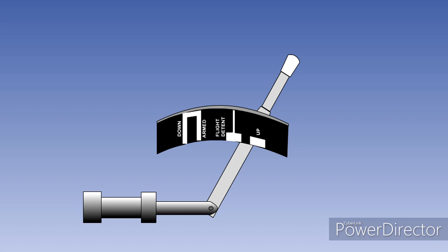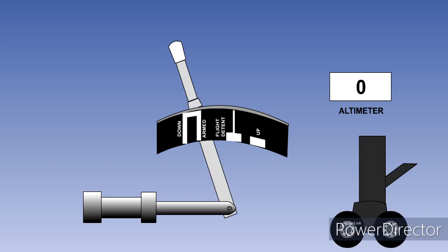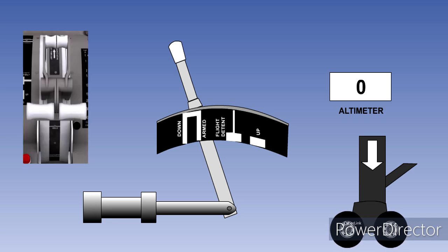Different aircraft types use various different parameters. They will usually include 2 or more of the following: the radio altimeter reading less than 10 feet, the wheel brake anti-skid system sensing wheels spin up, the air-ground sensing system giving an on-ground signal, and the thrust levers being fully closed.